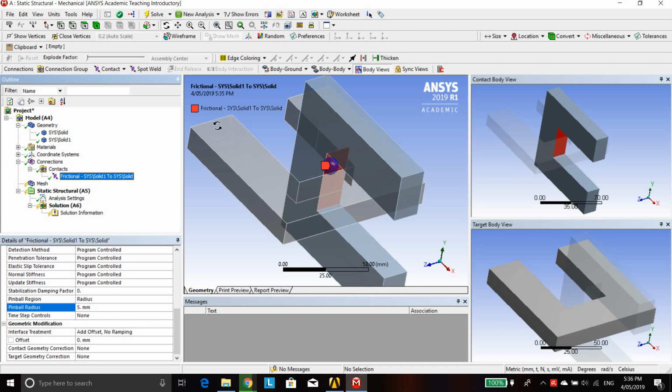It is going to be like 1,000, depending on the number of nodes you have. It's going to be a lot of calculations. But we know it's not necessary. You can see the geometry, and you can tell ANSYS, by the way, if you are looking for the contact for a node, look for just 5 millimeter left, right, top, and bottom. Don't go all over the geometry and look for it and waste our time.